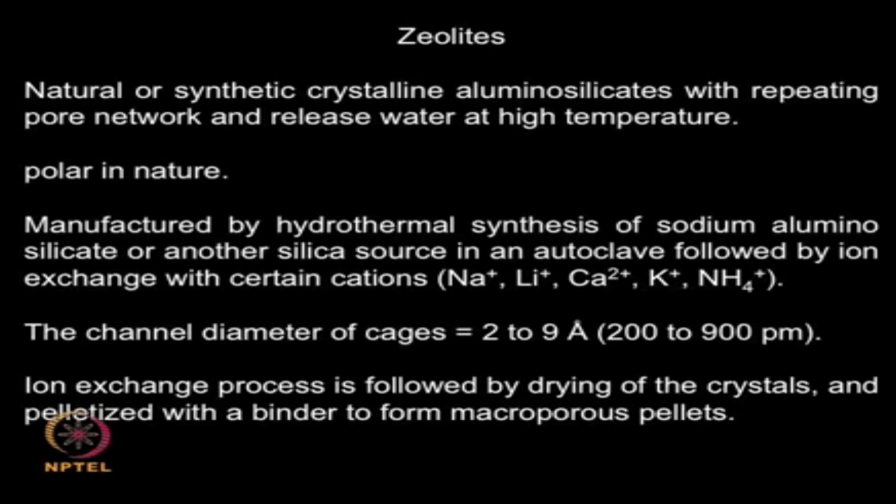So the dimensions can be between 2 to 9, or nowadays they even have large diameter zeolites. The advantage of, say, a small diameter is that it will preferentially capture only small diameter molecules, whereas the large diameter molecules go away. So it is almost like a filter, you just slow down molecules of that size which get entrapped inside the zeolite cage, whereas larger molecules which cannot enter the zeolite cage get flushed out or washed, so you can separate out small molecules as against large molecules.